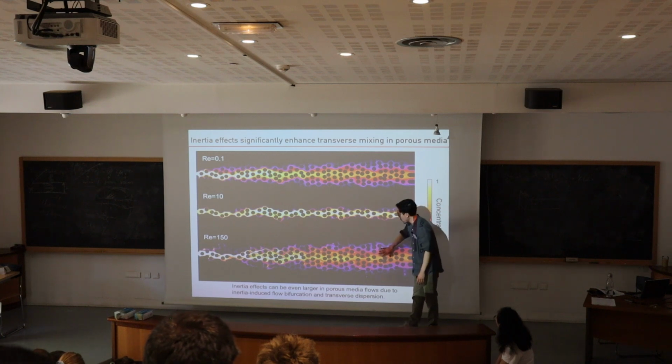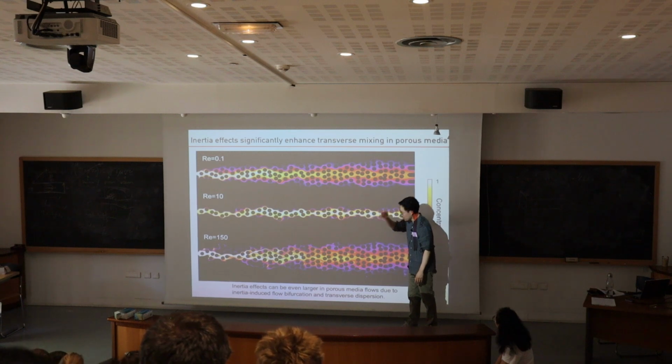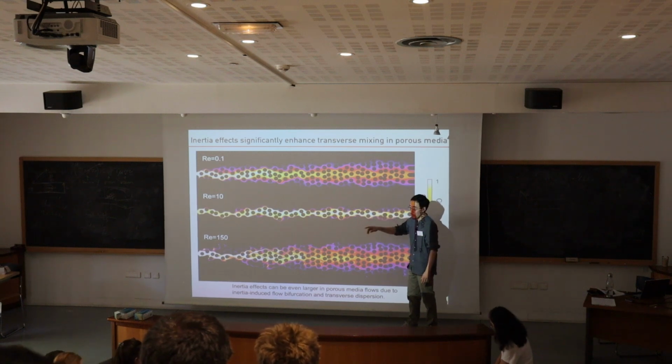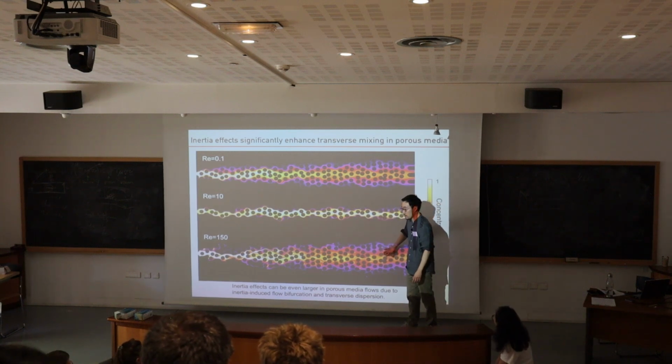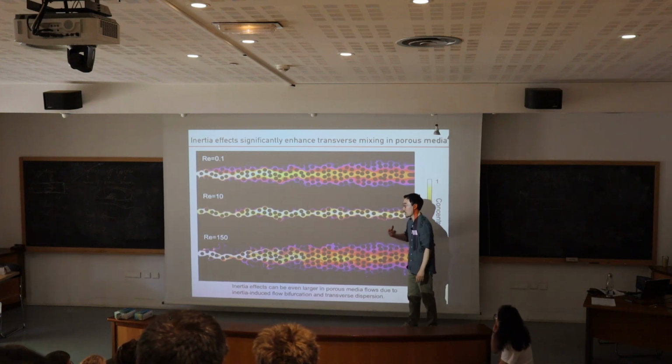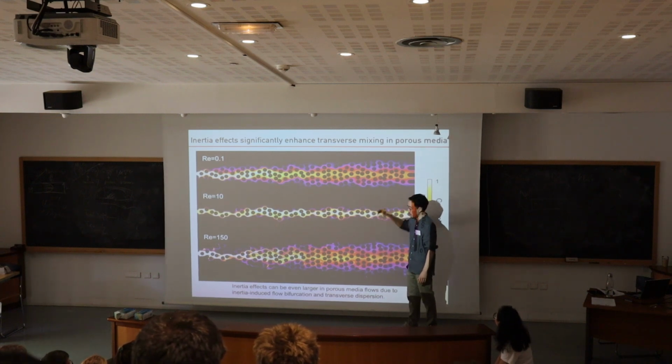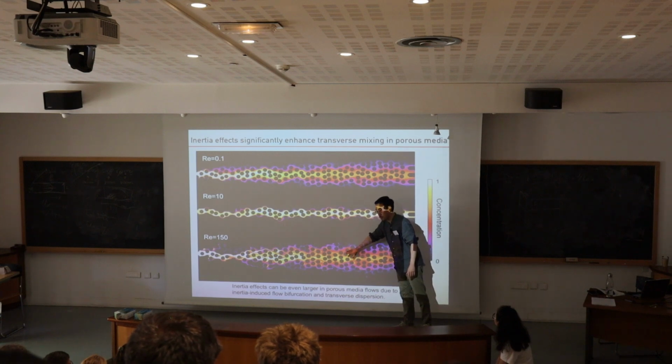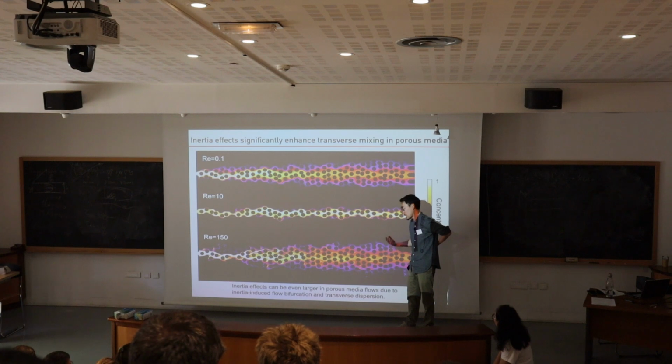So yes, we have to be careful because there's also the unsteady inertial laminar regime. In microfluidics, we can easily reproduce the unsteady inertial laminar regime, but I didn't even try to get into turbulent flow because pressure will go up really high. And the length scale is like 10 to 100 microns, right? So in that case, in order to get to turbulence, in my opinion, it will be really hard. Yeah, maybe that's the definition of turbulence here.